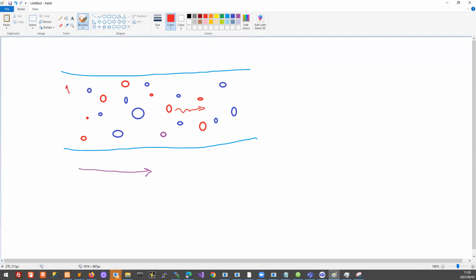So here we have a high concentration of A, and here we have a low concentration of A, and that's across the whole pipe. So let's say across the whole pipe, there was a certain concentration gradient in A. So low concentration of A here and high over there. And so overall, in addition to the fact that the whole fluid is moving, we also have that A is trying to diffuse in this direction. So the velocity of A will actually be greater than the bulk velocity.